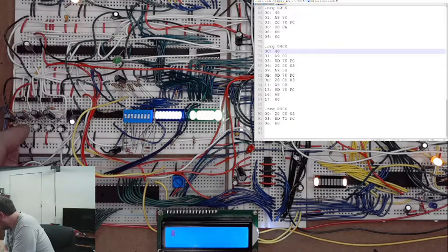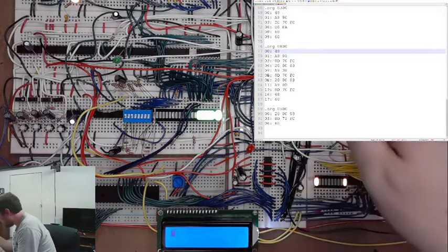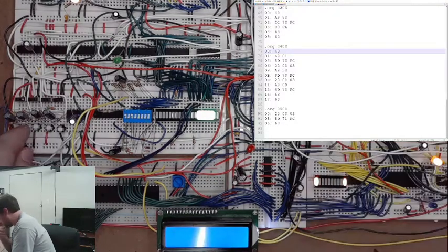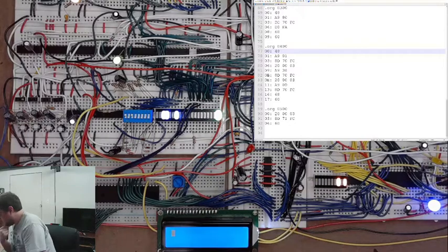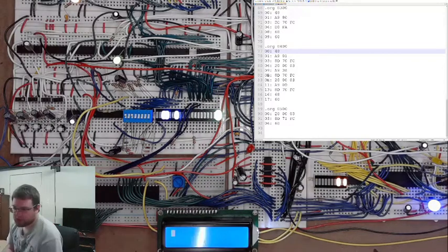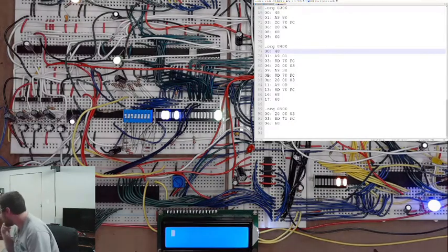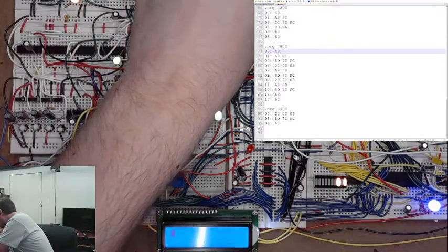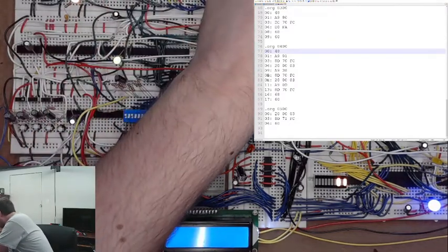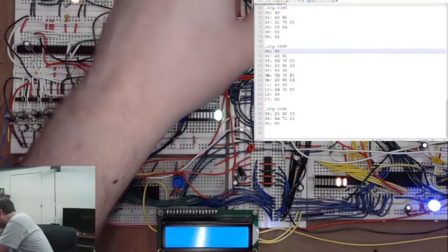There's still something weird going on with the processor. It always feels the need to do weird stuff. Because when we're going through the reset, here's what I expect. The reset vector. Yeah, that's what that is. 4C, which should be a jump instruction. And am I in the emulation mode anymore? That is the question. I am still in emulation mode. We're still good there.